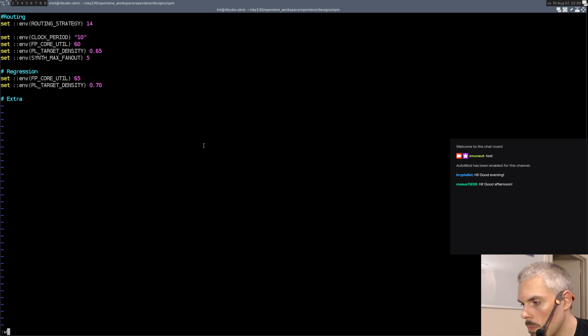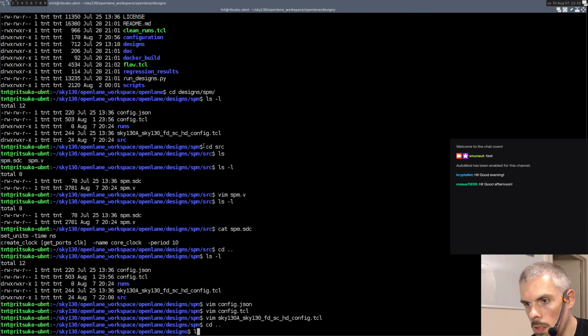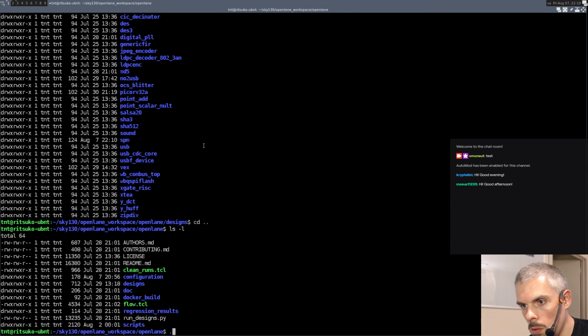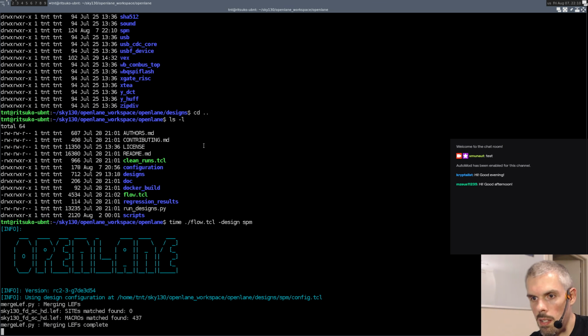It's newer, so I'm just gonna use that one. So let's just run that design. We just call flow.tcl. We say that we want to synthesize the design SPM, and well, let's just do that. I'm gonna time that, and it will start doing its thing.